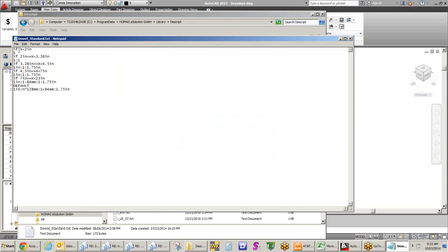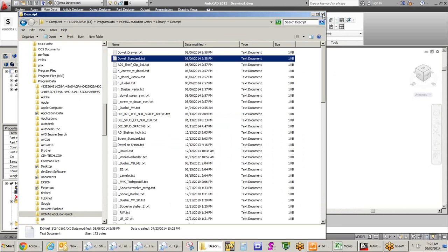Yeah. So now we can say that it's looking to say, hey, if this thing and its width is going to be less than 2 inches, then put it down in this way. If it's between this and this dimension, do this. These kinds of things. So you can literally very easily control and change construction methodologies by being able to determine which of those you want for each part type on the fly. Instead of having all of these extended formulas to do things, if you notice, I had multiple top conditions. So in one case, I could be throwing in stretchers. In the next case, full tops. I could have the same kind of thing happening with dados, literally any kind of controls that you want.